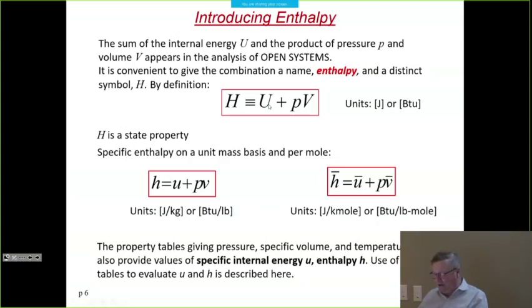All right. So in your tables, as we have seen before, we had rows for temperature, pressure, specific volumes, internal energy, and enthalpy H. And then we had this mysterious thing that was called entropy. But the fact is that you can use H or U or V just as well as you can use P or T as the intensive variables that you want to use to characterize your system.